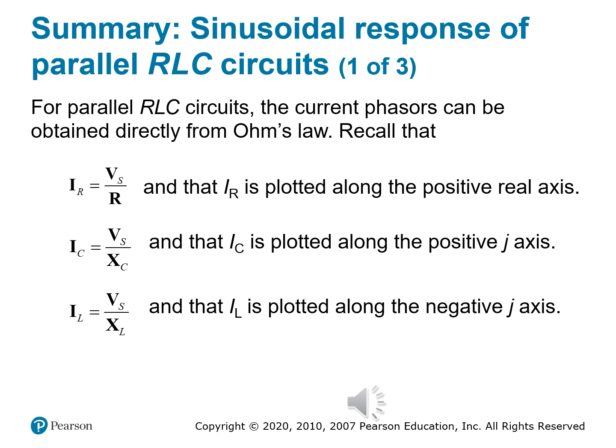And then we have finally I sub L, which is equal to V sub S divided by X sub L, that inductive reactance. And with the inductor, yep, you guessed it, it's always lagging. So it lands on the negative j-axis.